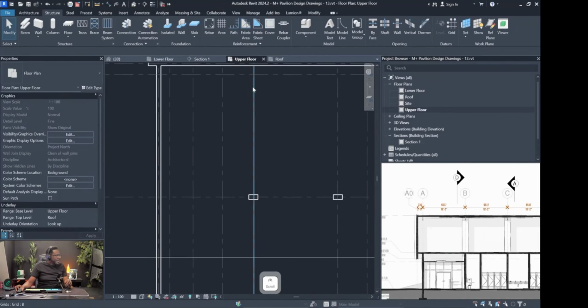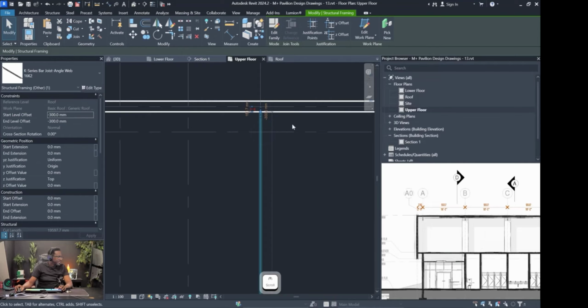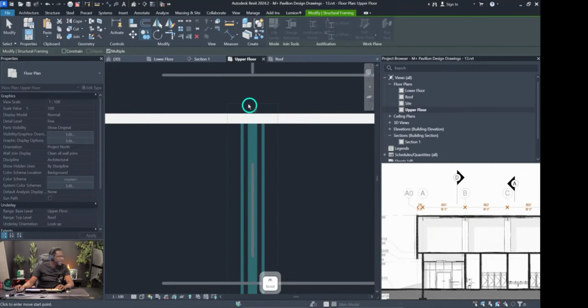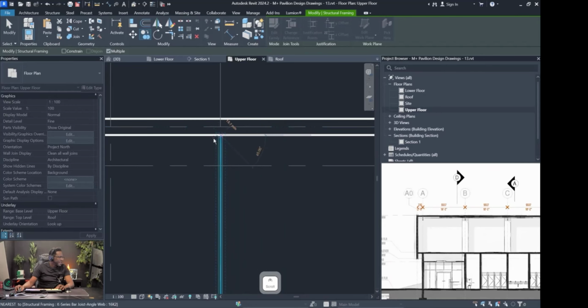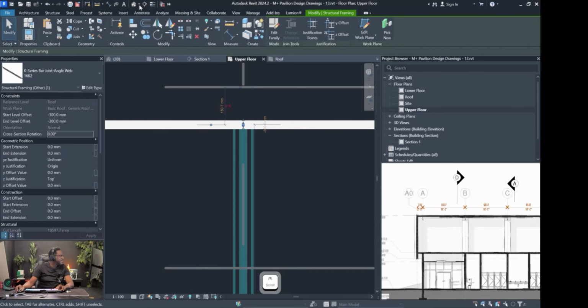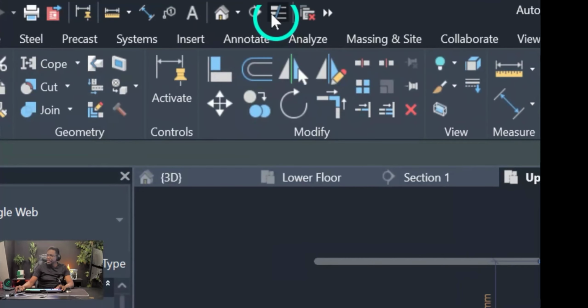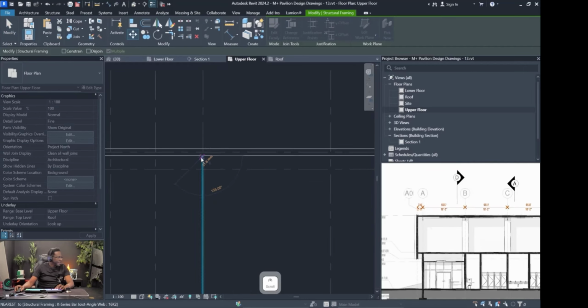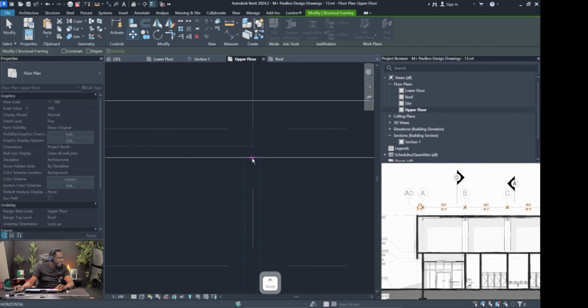drawing here. So with that said, we are gonna choose this beam here. We're gonna go CO copy, and we're gonna copy it. I'm gonna make sure to grab it in the center. And what we can do is I can always turn off the thin lines here, so that will show me with the thin lines. Copy this here. I'm going to paste it right here. Let me make sure that that is in the center.